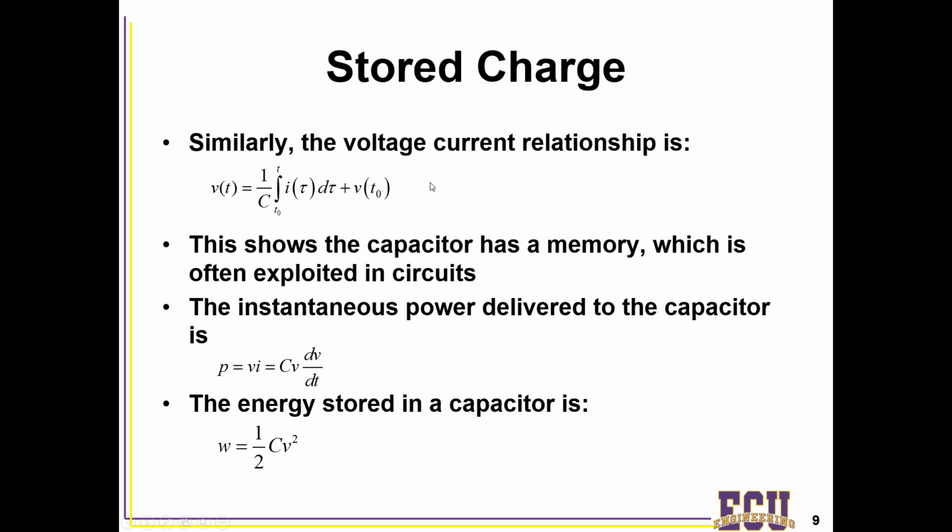What the initial value means is we have some memory. Capacitors ideally will store charge until the end of time. If we have an ideal capacitor, we put some charge on it, and then we just disconnect it from a circuit and put it on a shelf, ideally it would hold that charge forever. That is an important thing to note. If you have a circuit with any capacitors in it and you cut power to it, that capacitor could very well still be holding on to some charge.